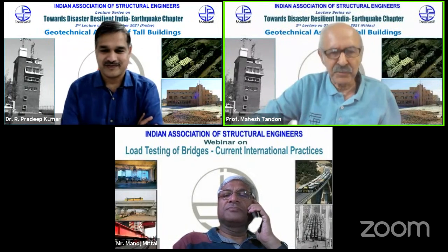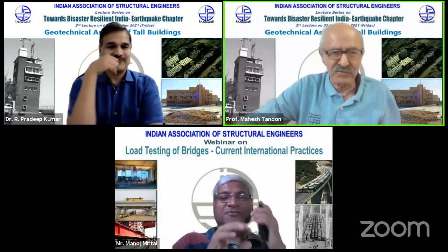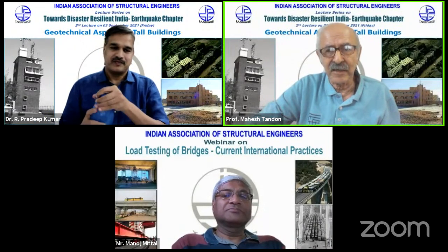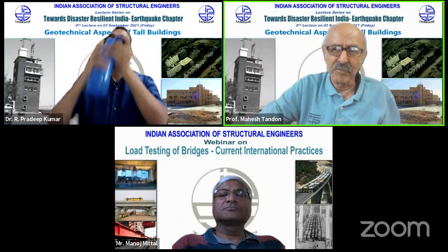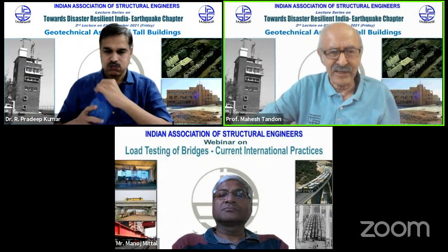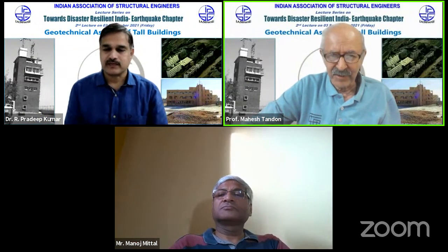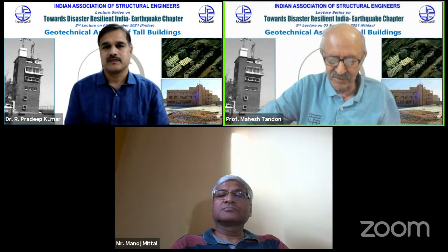Professor Pradeep Kumar has concentrated on three issues which relate to tall buildings. One is that just using the map suggested accelerations and designing a tall building is not adequate. You have to do a site-specific hazard study in order to design the tall building. That's the first thing he has mentioned.